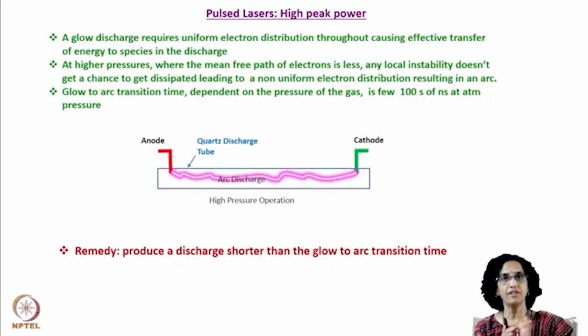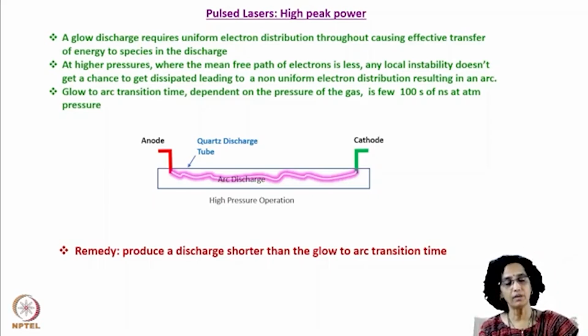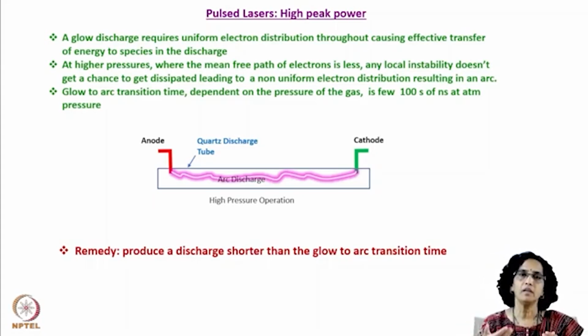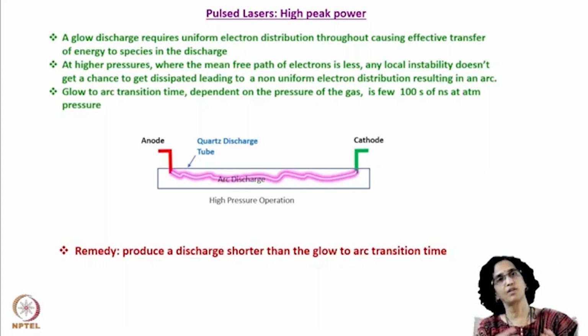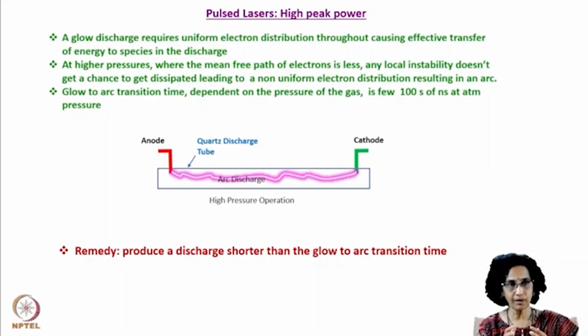So far, we have only seen how to increase the laser output power in CW condition, and we have seen that we can increase it by increasing the gain medium, increasing the length of the cavity. We are replenishing the cavity gas mixture very fast, so that newer and newer gas mixture comes into the system, and you can pump it harder, try to get more output. So these were the ways: fast axial flow, transverse flow, or large cavity lengths, segmented discharges, V-shaped cavities, etc. were part of that.